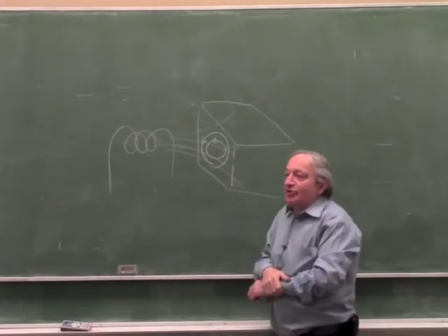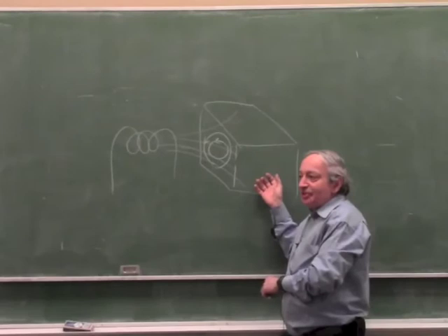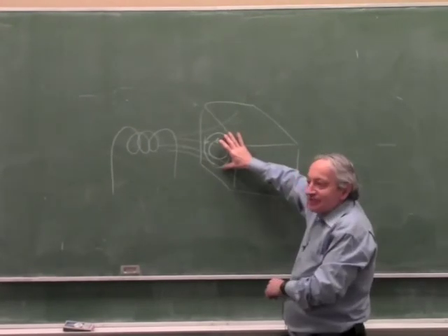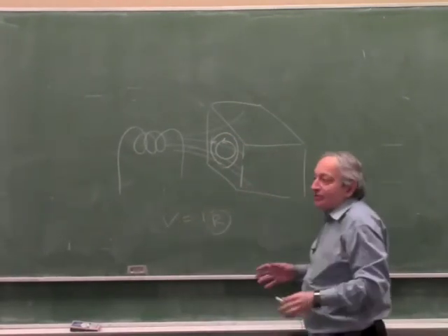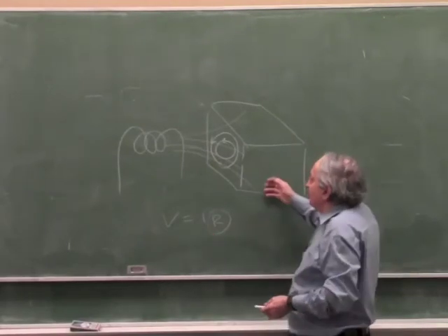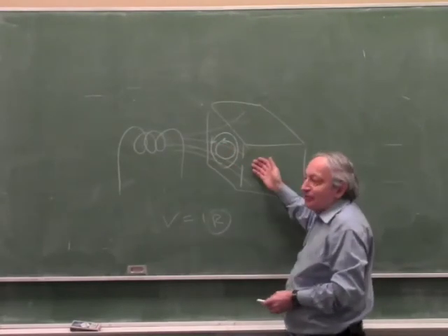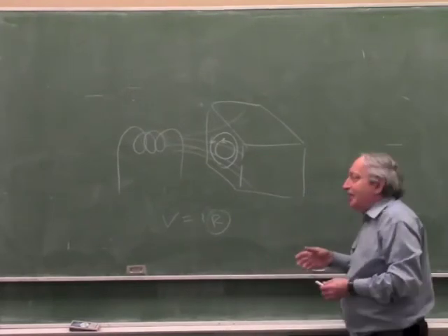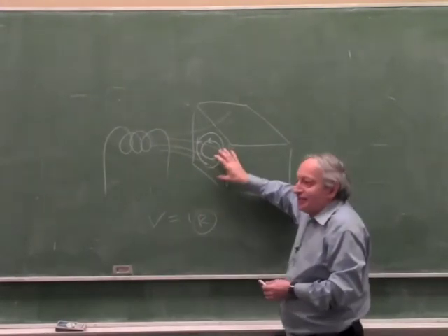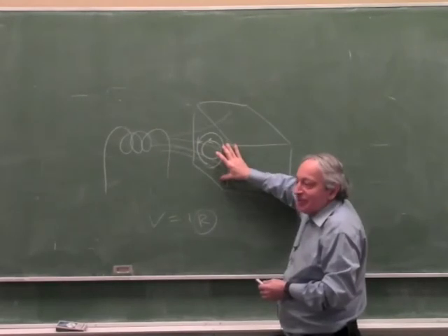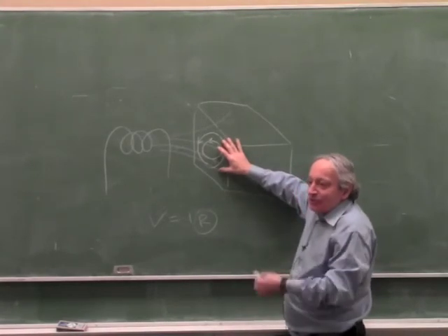If this box was a superconductor, it would be a perfect shield, because a superconductor means zero resistance. Now, zero resistance means you cannot have any potential difference, because V is IR, but if IR is zero all the time, you cannot have V. So if this was a superconductor, there could be no potential difference, there would be some surface current, but inside there would be no field at all. But with practical materials, steel is good against the magnetic field, but then the steel has high resistivity, so it actually allows quite a big potential difference. Copper is a good conductor. It doesn't allow high potential difference, but it doesn't stop slow magnetic fields.